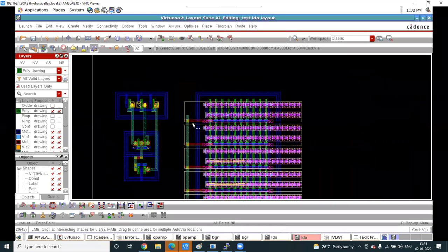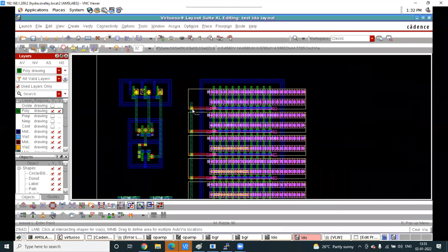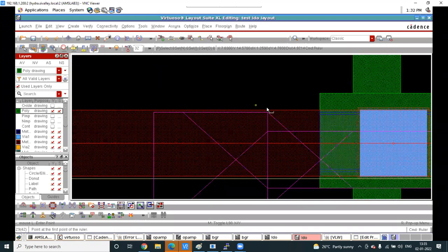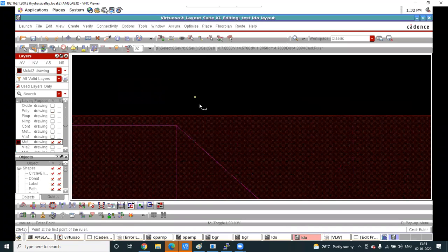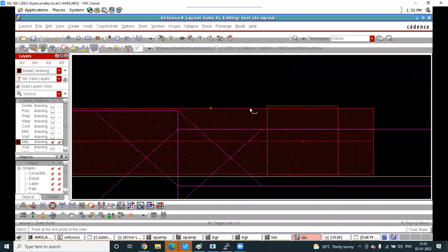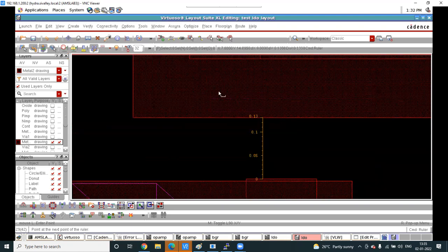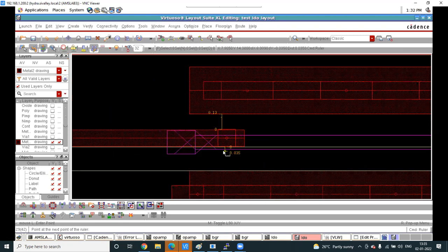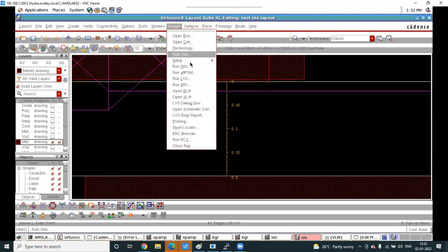Okay. So this is the way. If anybody has a doubt, even if you face DRC, let me know. Might be M2 DRC, then we will do something different. I think it will not be spacing. What is the minimum spacing asking? M1, M2 to M2? I think other DRC will not be there.